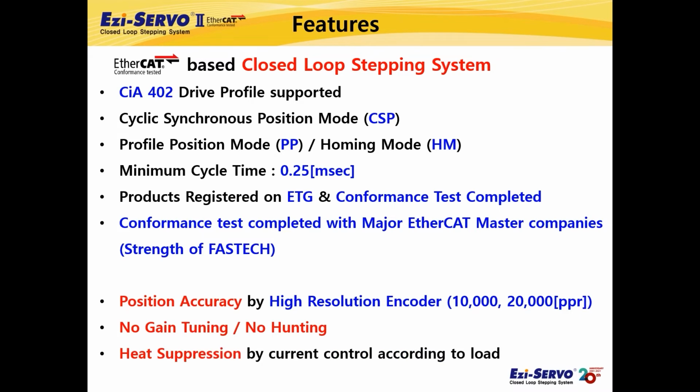In general, when controlling a stepping motor, motor heat is a problem because the maximum current flows regardless of the load, but since Ezi-SERVO controls the current according to the load like a servo, it can relatively suppress heat generation compared to the conventional stepping motors.